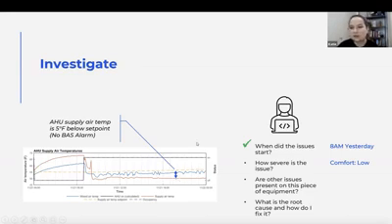If I were a technician, I had a campus I was taking care of, and I went in the morning and I looked at my BAS, like I always do, to see if there's anything that sticks out before I go and take care of my work for the day, I don't think I would prioritize the 5 degrees below set point. It's probably not impacting the occupants. They are probably reheating to overcome it, but not a lot. And I've got, you know, a toilet leaking across campus or whatever it may be. So I would maybe stop by there before lunch, or maybe on my way home if I had time, but it wouldn't be something I would prioritize.